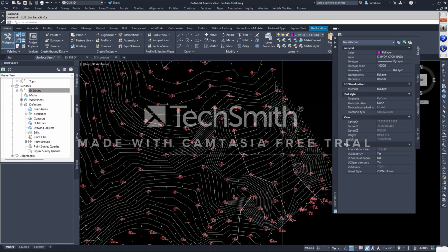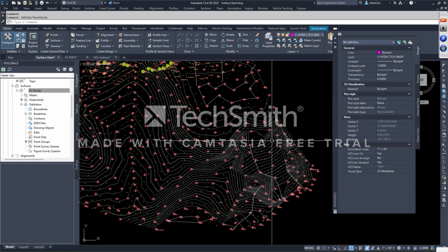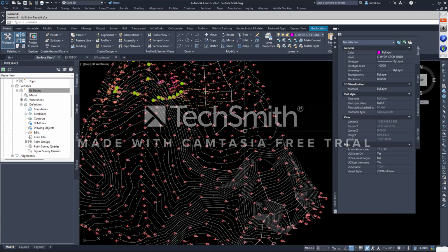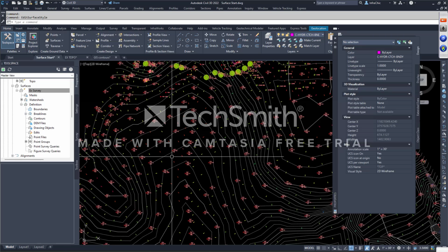It lets me know the way the water is flowing, or in this case, the way the surface is flowing. What is the slope of this arrow, of the area? This is really handy when you're looking at things going, is this right? Is it doing the swale right? Yeah, it's doing the swale right. Sometimes I'll turn these slope arrows on while I'm designing and just make sure my surface is right. And as a surveyor, leaving those slope arrows on as you go in and add in your break lines will be very helpful, believe it or not.